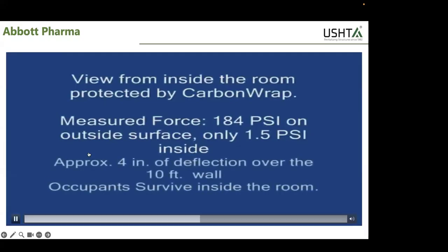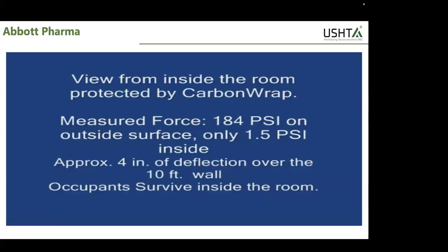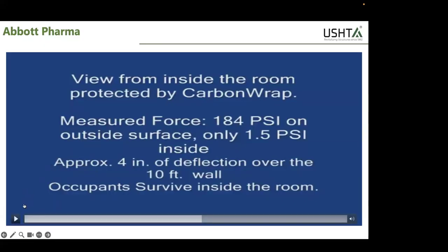Here it is very important to see this. I'll just hold for a second here. The measured force outside was 184 psi, and inside it was just 1.5 psi. The approximate deflection was 4 inches both ways in 10 feet of wall, which is AAC blocks. You cannot expect that, right? I'll show you the side view of this, which is very interesting.